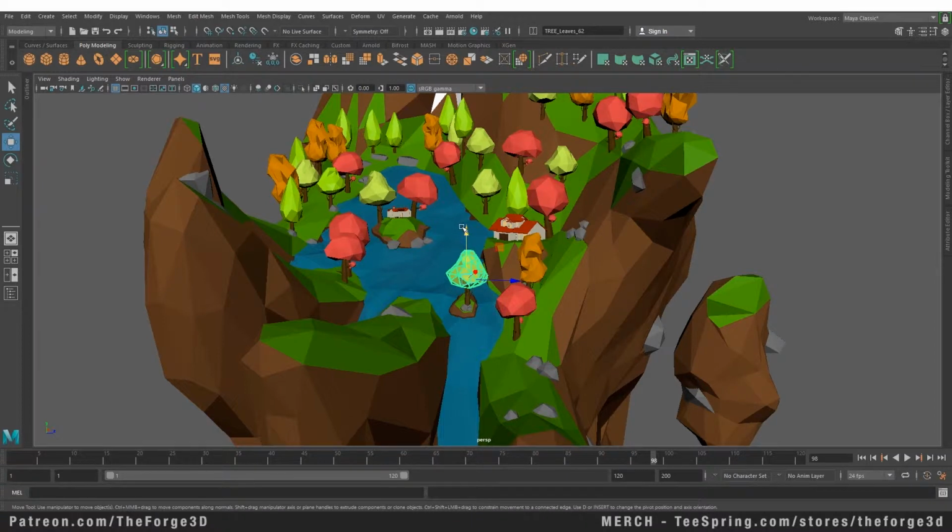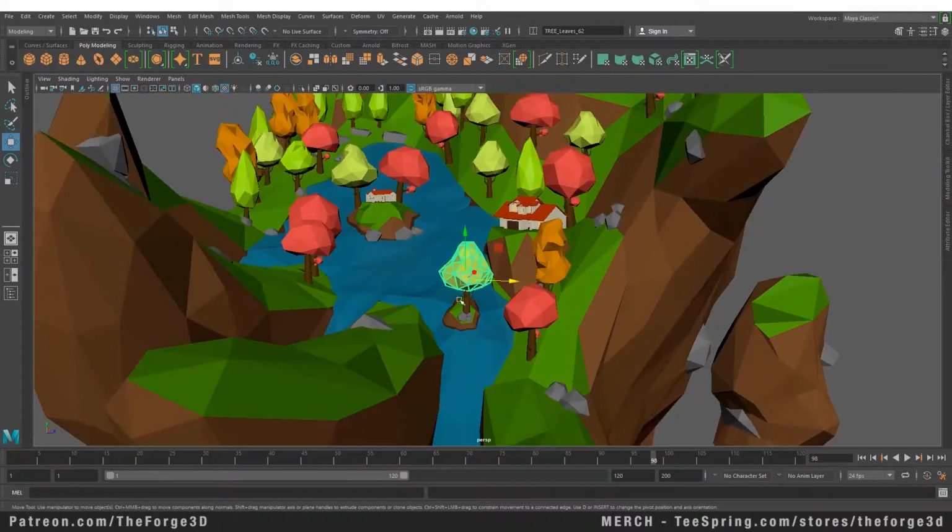The green axis is right now yellow, which is to indicate that we have the y-axis selected. Any axis that you have selected currently will show as golden or yellow. So if I click on the z-axis, you can see that the y-axis is green. You can also move the object by clicking at the center of the pivot. This allows you to move the object in all three dimensions at the same time, which is highly inaccurate unless you're trying to snap that object to something else.